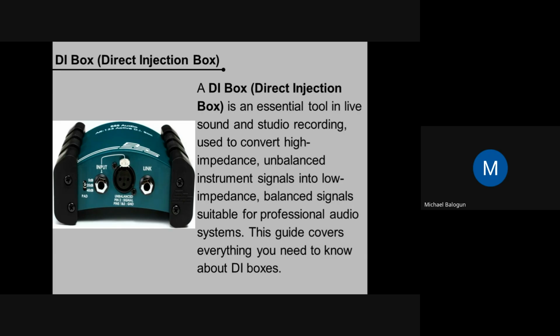Sometimes some of us are not disciplined, whereby somebody's hand is wet or they just came from the rain and just mount it. It is dangerous. That's why here you can't find any instrument that is connected directly. You use the DI box. It's a crime if any engineer just plugs an instrument directly. Even if you want to play back from a phone or from a laptop, you still pass it through a DI box. That's the standard.